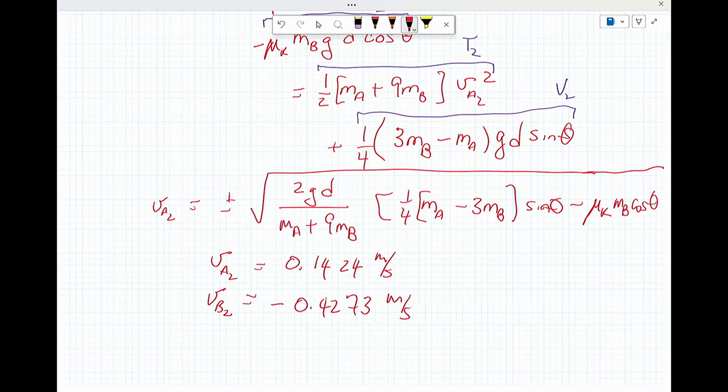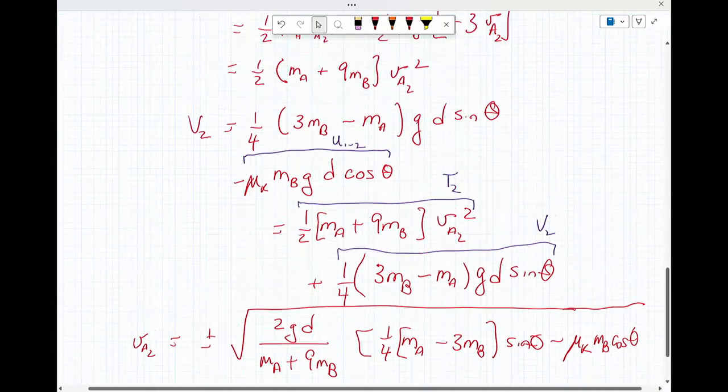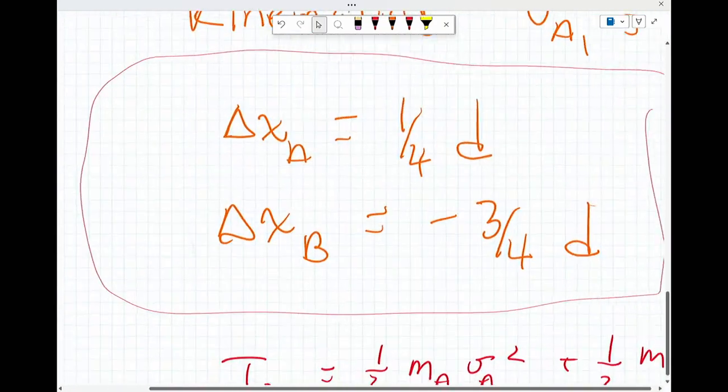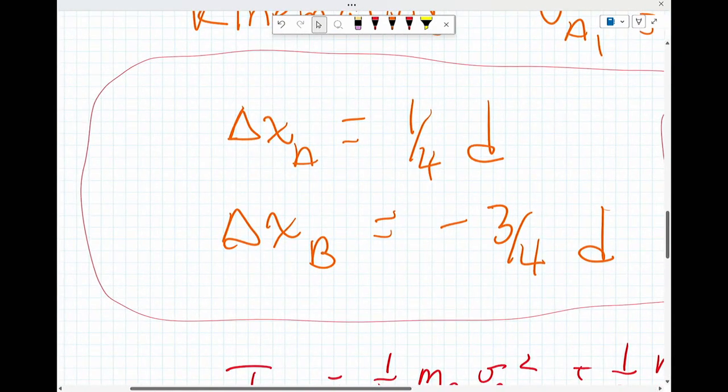So it's a straightforward application once you have everything written out, once you have all of the displacements correctly done. The tricky bit is really this bit here, and recognizing that one is traveling a different distance than the other. And that's where you're getting your internal work term.